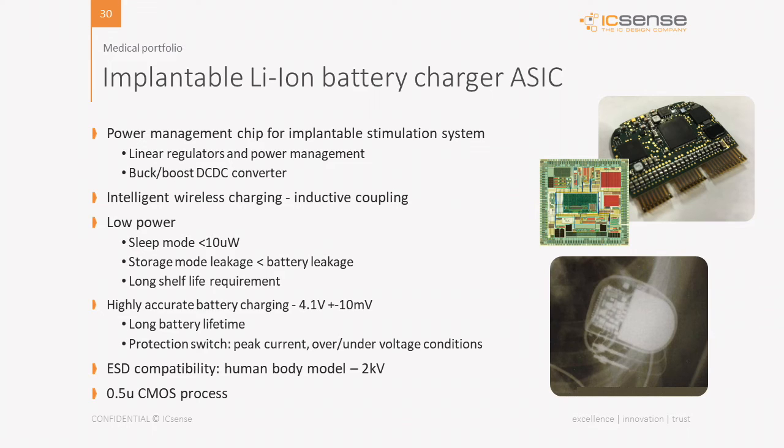Another example is the implantable lithium-ion battery charger. For this client, we have developed a power management chip that can be used for implantable stimulation systems. This chip contains the regulator, the power management, the boost DC-DC converter, and a lot of intelligent wireless charging circuits.